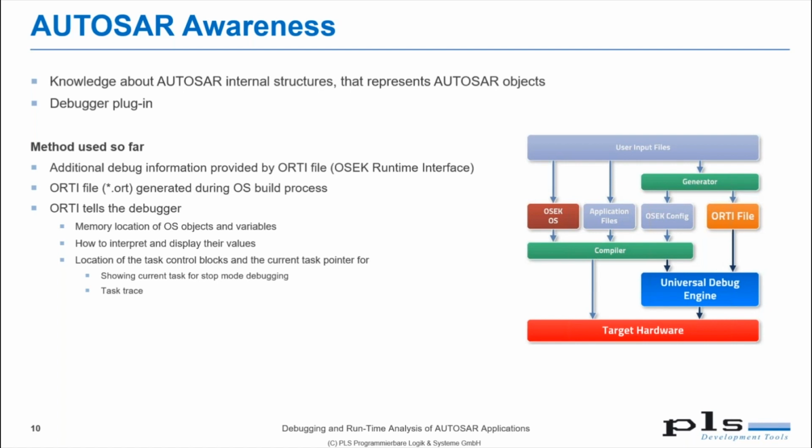Up to now, the most common way to provide this information to the debug tool is to use the so-called ORTI. ORTI stands for OSEK runtime interface. ORTI defines a file that contains all the necessary information that is used by the debugger to show AUTOSAR specific information.